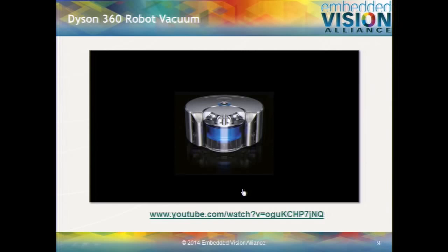Not just in a straightforward way that you might think of, looking around, but actually using 3D vision to create, in real time, a 3D map of the room and everything in it, at least at floor level. Now it has a model of the space. Now it can map out a path through the space that never collides with anything and covers each patch of floor once and exactly once. A vastly more efficient approach, but only possible really with vision or some comparable sensing technology.